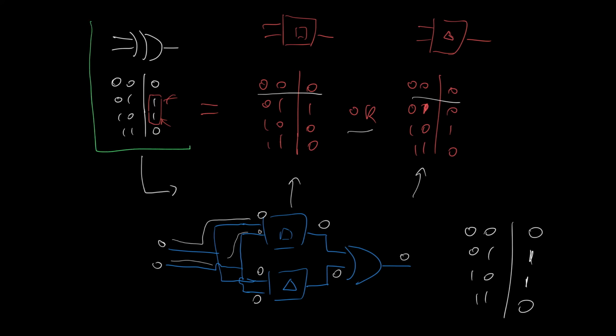A plus is a sum. We sum things up, we add them up. And remember, I said at the start that we're going to write this truth table in a particular way as a sum of products. And here's our sum. We've got an OR gate here. We just have to write these guys here in terms of products or AND gates. And there's a special way we can do that as well.